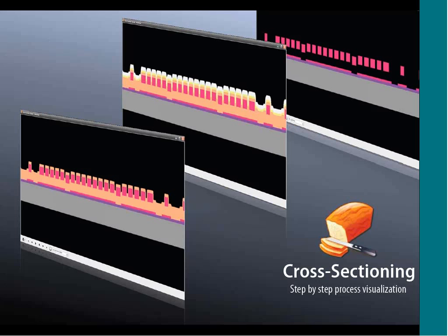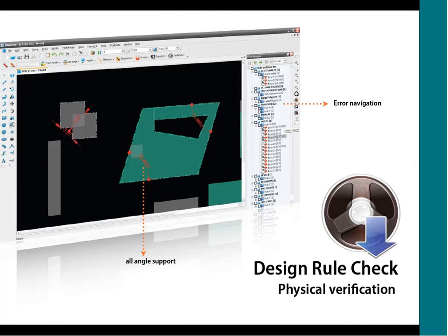One neat thing that you can do within the layout editor is link it with the process flow that you built up, so you can quickly look at 2D cross-sections if you are developing and designing your mask layout and you want to see how it's going to look when it's actually being processed. And we also have a lot of other capability, which I won't touch on today, but things like design rule checking and scripting and other functionality that's very helpful for MEMS development.